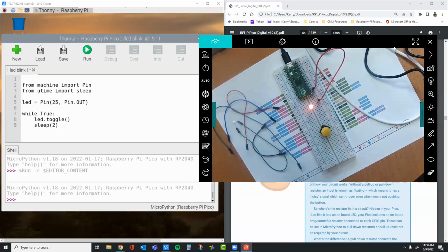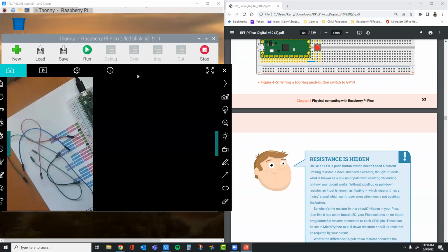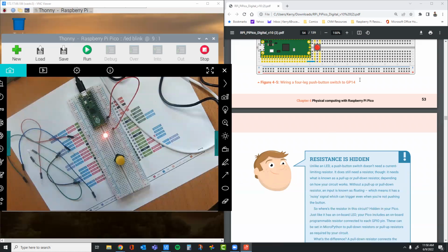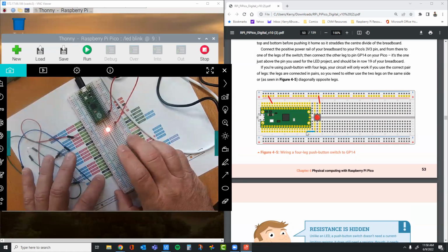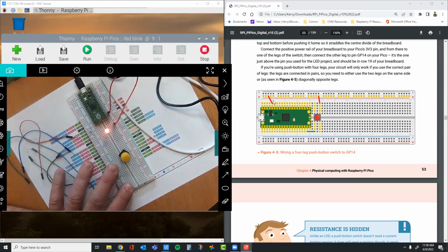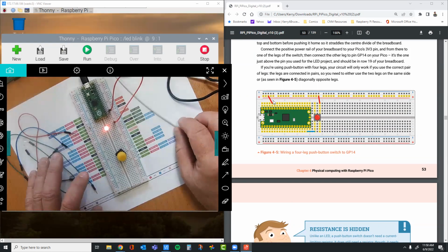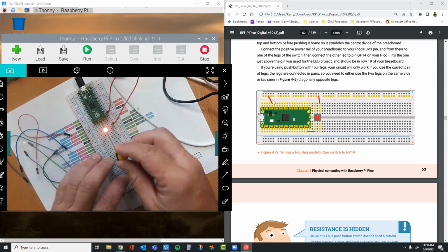Okay, so let's take a look at the wiring here. I want to put this wiring up so we can see what's going on. They have us connected to a different ground this time, it looks like. Actually, what's going on here? They have us connected to the second, so 14. You can see I'm connected down here to 14. And over here, I'm connected to 1, 2, 3, 4, 5, the fifth one down, which is 3 volt power. We don't have a ground on this one because we're just running power through it. Okay, we'll see how that works.